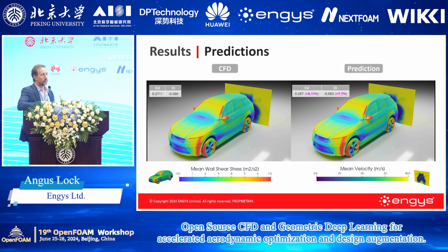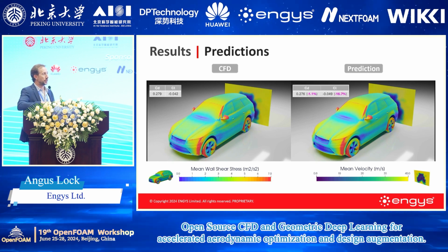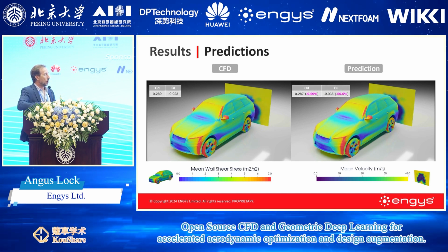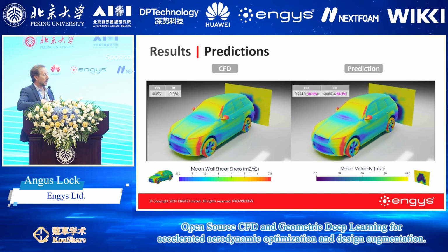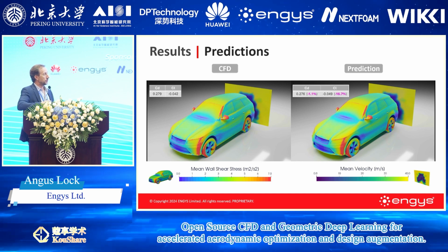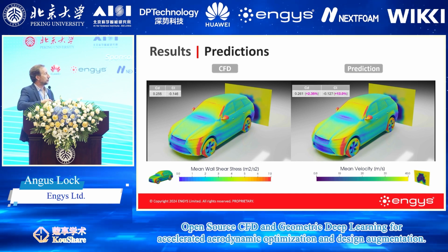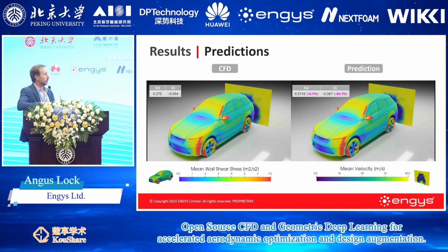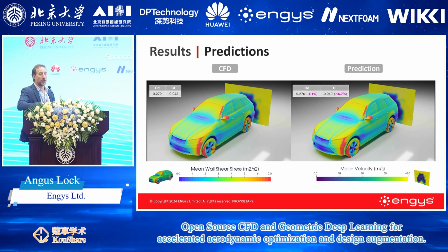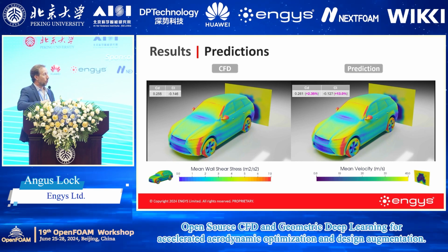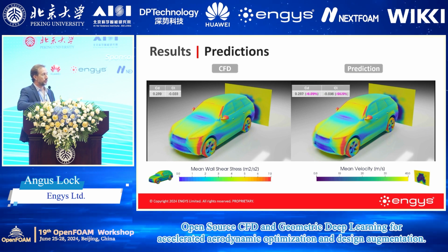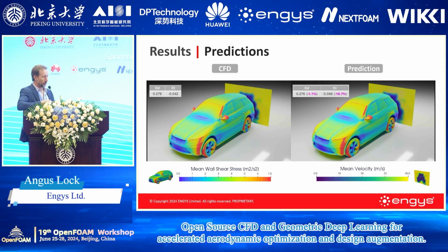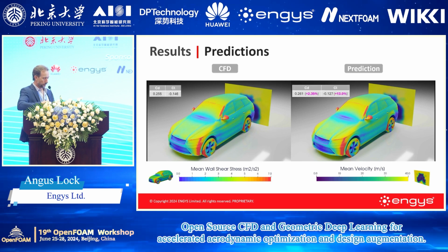So this is really interesting for me as an aerodynamicist to be able to use this graph neural network output in my day-to-day activities, because I not only see the change in the drag coefficients as you morph the object, but you actually see the flow field and try and understand what the morphing is doing, what changes are being caused to the flow field to result in these changes in the force coefficients.